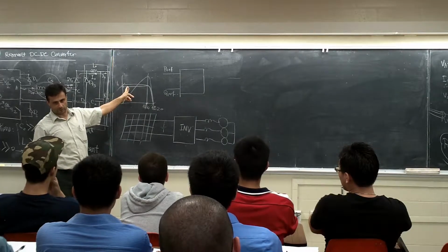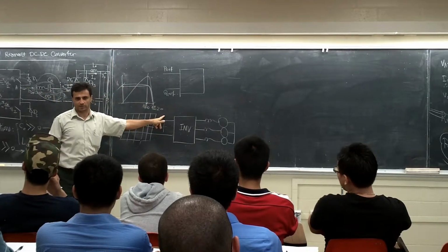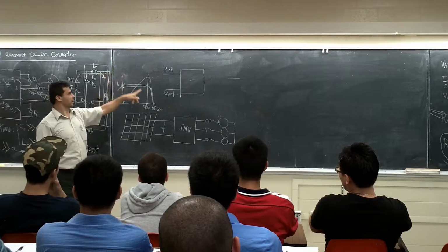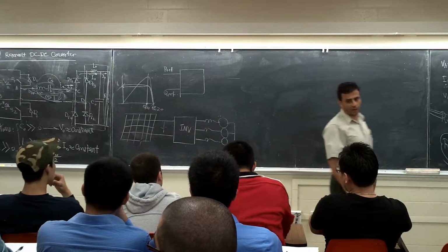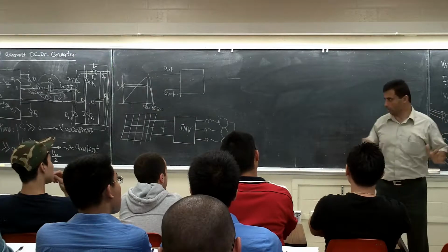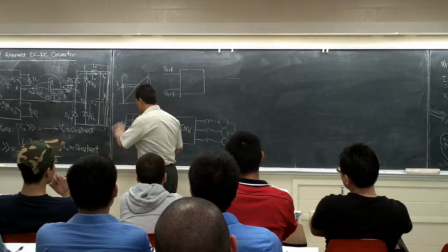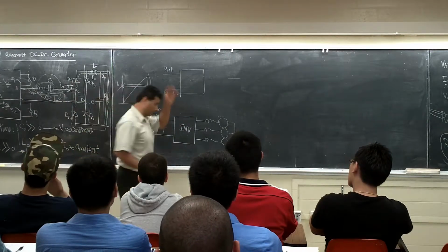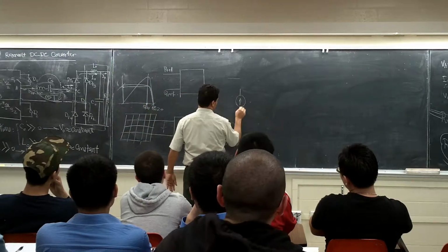If you look at the PC model, the short circuit and open circuit are easy to find out, because you know how much this is times 8, and this one, whatever it is, you're going to put it there, 6 amps. But you can find this one from the Excel sheet you have. Now, the solar panel you modeled in the PC, before going even here, forget it. Don't put the solar panel here when you are going to do this one. You simulate this case. Put the current source here.